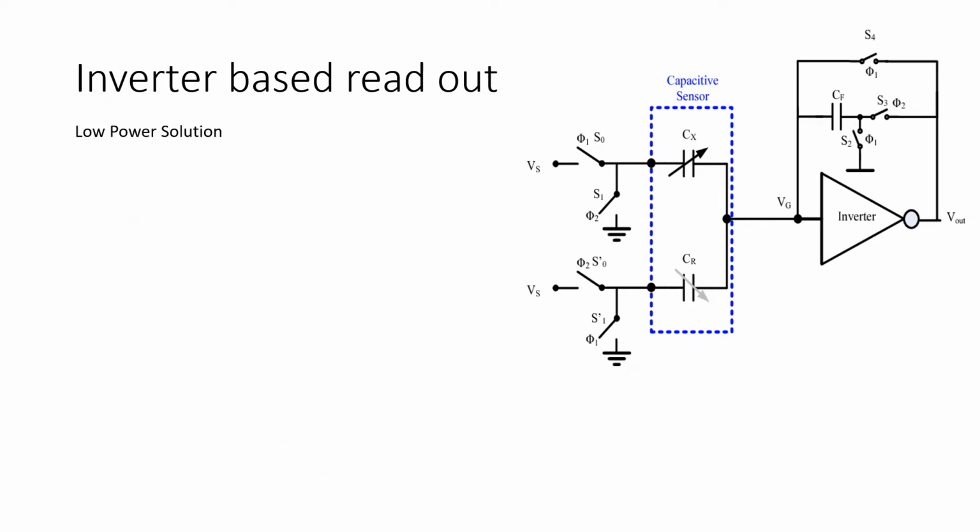A quick comparison for what it should be or what it could be if we replace the inverter with a high gain amplifier. We are looking at its operation in the inverting or non-inverting mode. We would prefer the inverting mode here. So here you have the input resistance. This is your feedback resistance RF. This is the output V0.